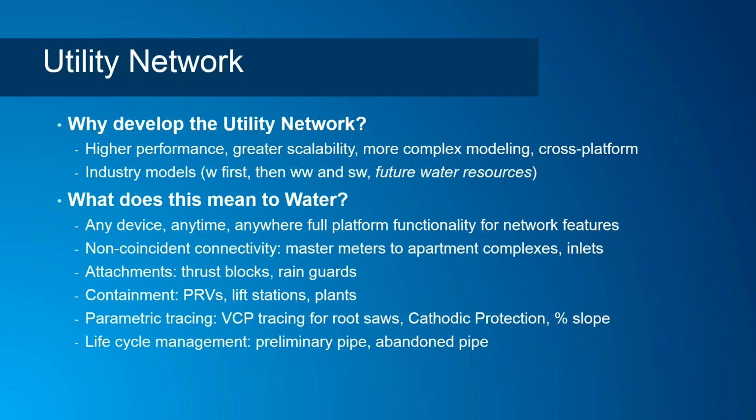Introducing also this non-coincident connectivity. You'll be able to connect things so that they can participate. And this gets us into, I immediately was drawn to master meters for apartment complexes. You can have all the individual meters, but you may have a master meter, for folks doing service points, and even inlets, with the stormwater folks. Some of these inlets, we just have point features right now, but we can start doing connectivity with these disconnected features, if you will,